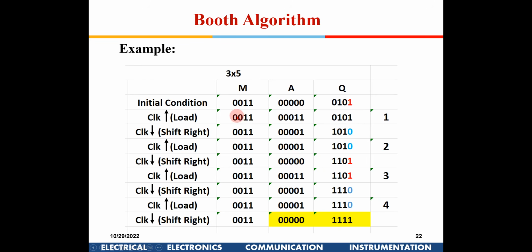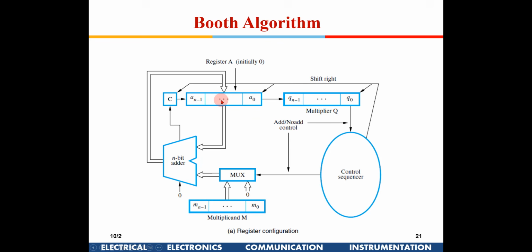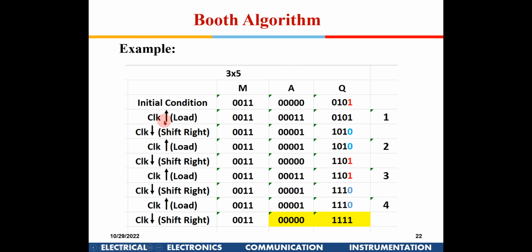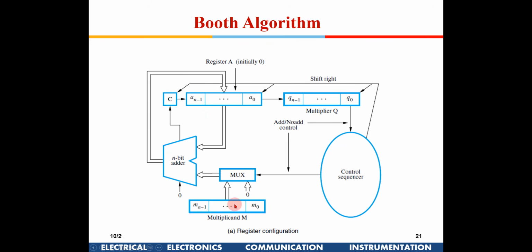So we learnt about mux based registers, shift registers, and universal registers in the last class. So we can use those kind of registers to do this particular operation. If you see here, M remains constant throughout, because this is B. Whether this requires to be added or 0 requires to be added will be decided by the last bit. But this particular register continuously holds the same data.